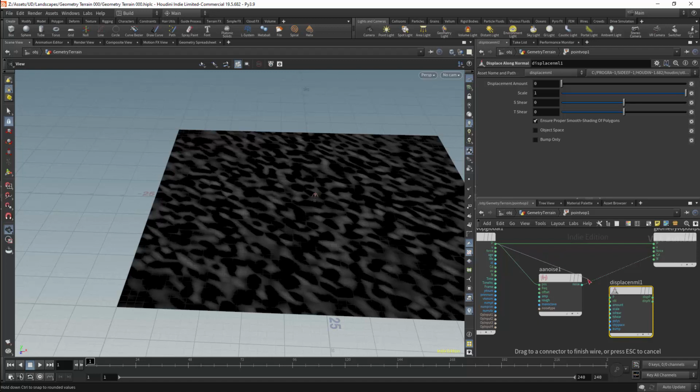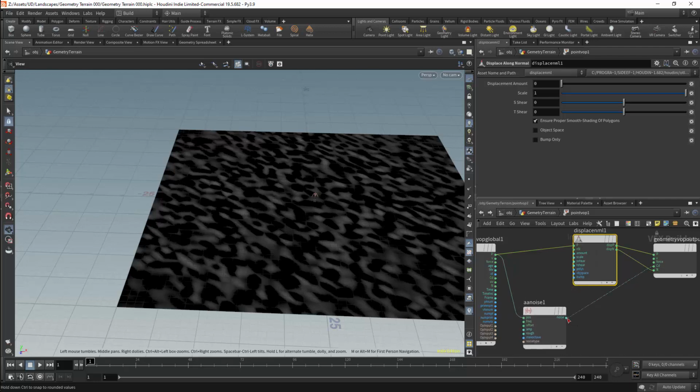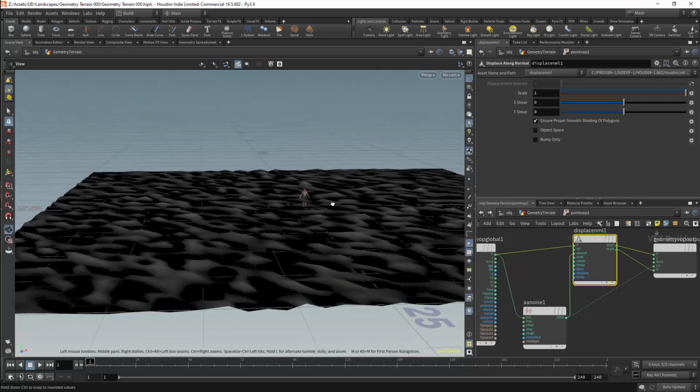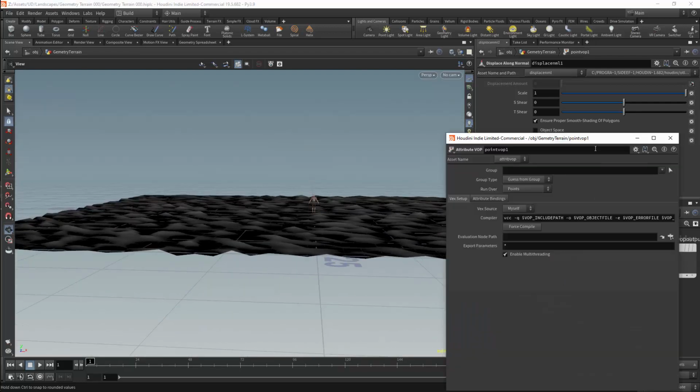We'll need to displace our points. We should also actually add normals to this, and feed the normals into our displacement node, but I haven't actually added any normals yet, so I can remove this connection for the moment. The displacement is displacing our points, so I'll connect the points in the displacement to the points on our output. I will also displace the normals. I'll then set the amount of displacement with the noise. And we should now be modifying our geometry. I'll open the parameters for the VOP, as I will want to expose some of these parameters within the interface.